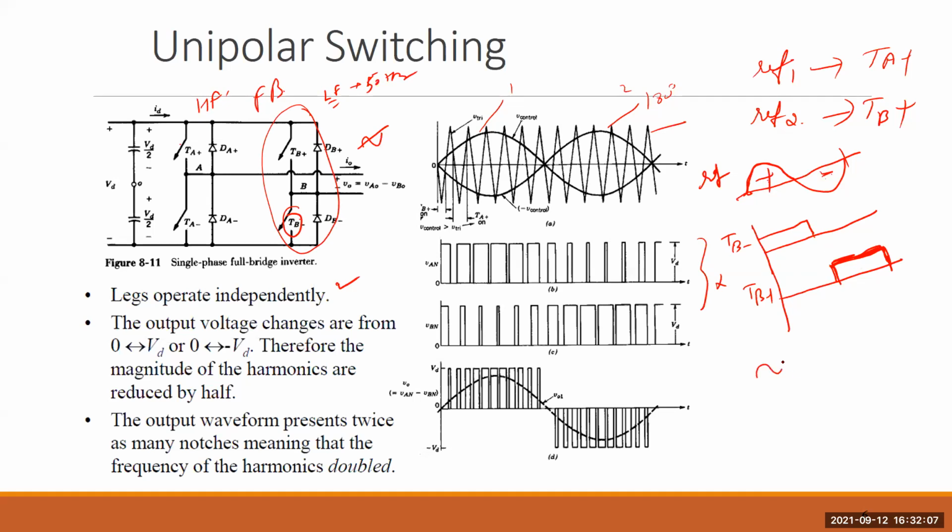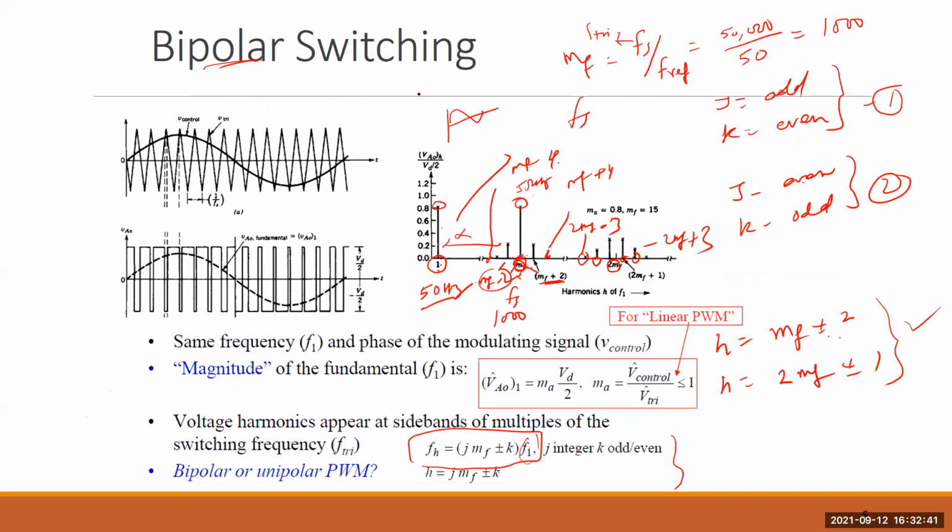So this is very easy to do. This is compared with a comparator, and this is ground, which is 0. When it is higher than 0 it is high, and its complementary is low. When it is lower than 0 it is 0, and its complementary will be opposite. So now actually only one reference will be sufficient. Just follow the first reference like before.